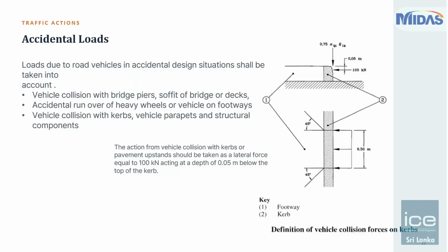So these cases will not govern. But if you have bridge sections where the decks are very slender, and you cannot discount for these particular loads, so we must account for the accidental loads on crash barriers, lateral loads.